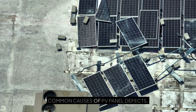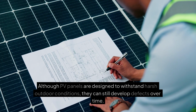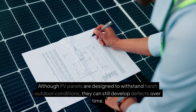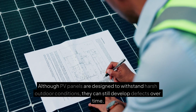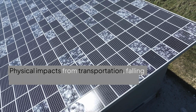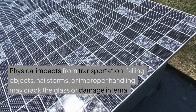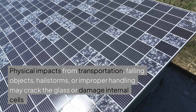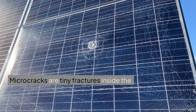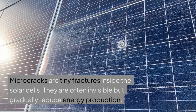Common causes of PV panel defects. Although PV panels are designed to withstand harsh outdoor conditions, they can still develop defects over time. Physical impacts from transportation, falling objects, hailstorms, or improper handling may crack the glass or damage internal cells. Microcracks are tiny fractures inside the solar cells. They are often invisible but gradually reduce energy production.